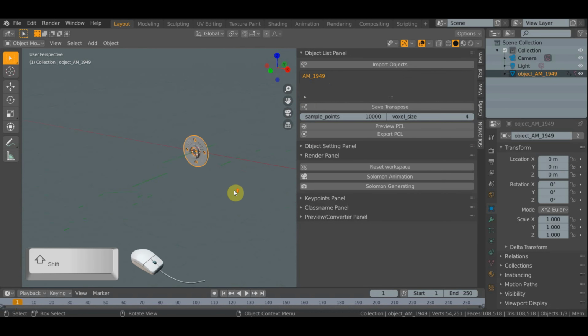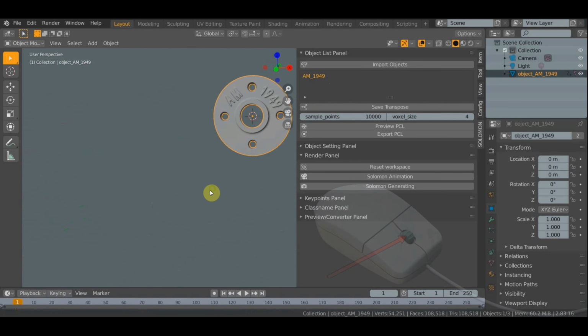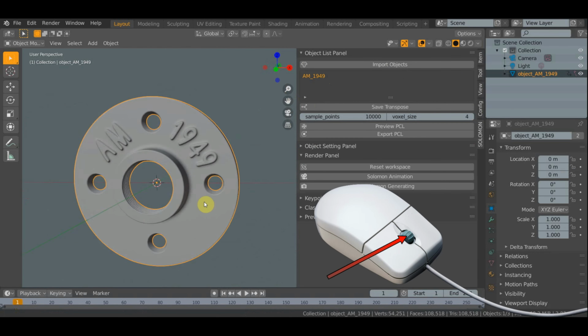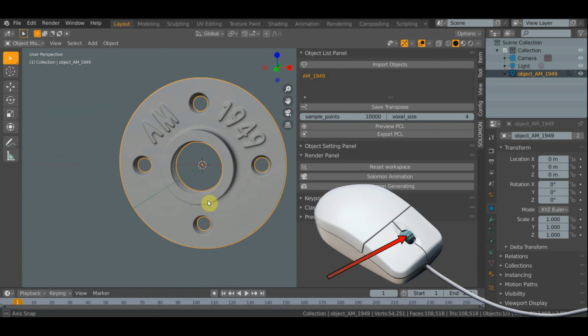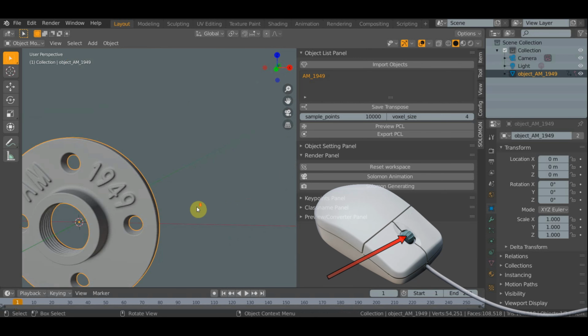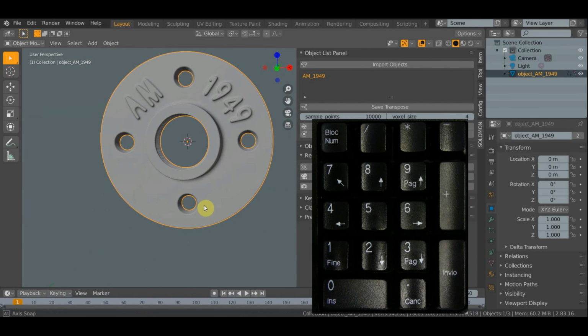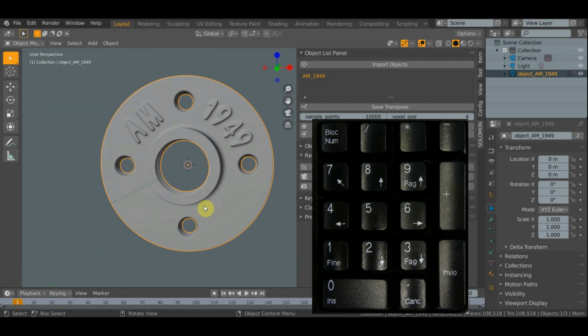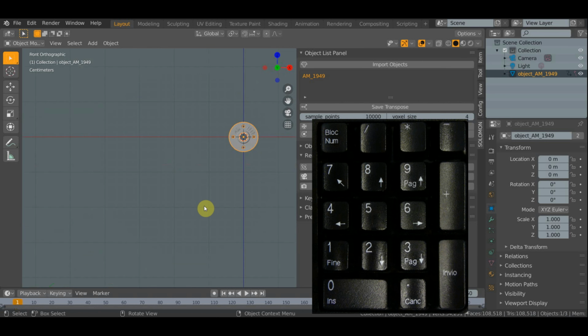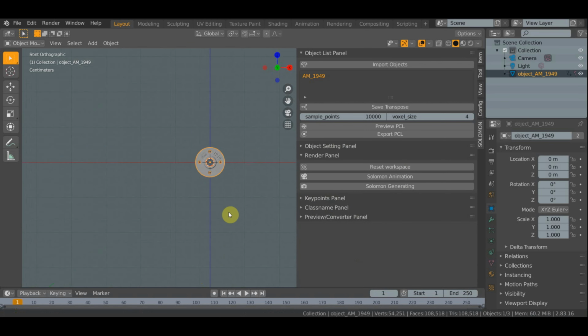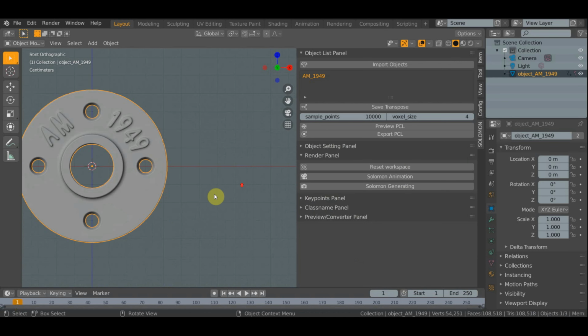To move the workspace and get closer to the object, you can use Shift button plus round icon from the mouse. To rotate the workspace, use the round icon only. To zoom in and zoom out, rotate up or down the round center icon. You can also press 1 in numbers block of your keyboard to automatically rotate the object and watch it from the white vector of the workspace.